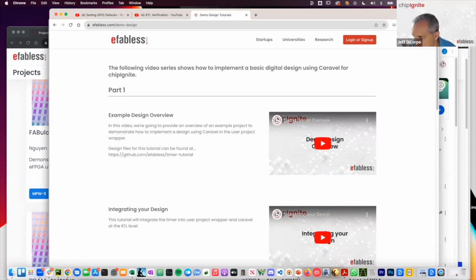Generally, I'm cautious about wading into a deeper, more complex conversation of when you need to modify the constraints. But for the base case, you should not need to modify them if you're just implementing a Wishbone bus slave interface in the project area.